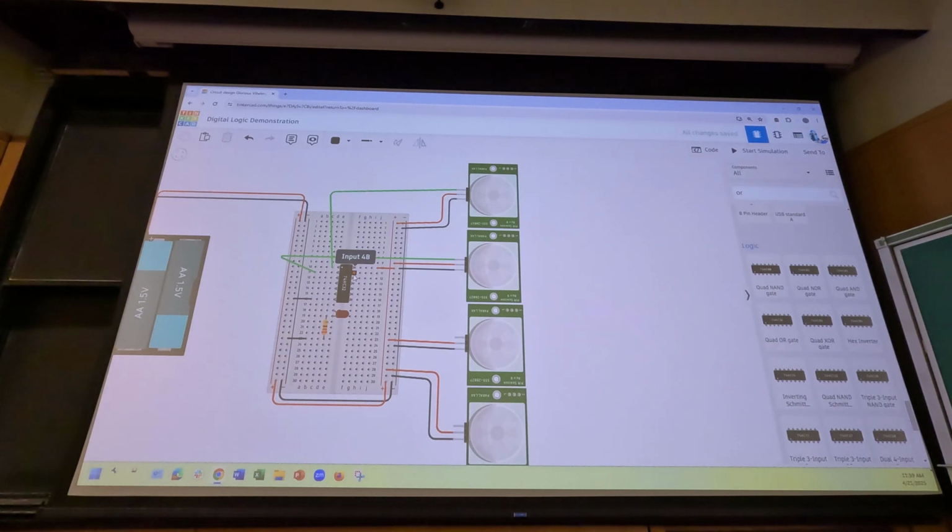There is a process to work backwards if you have some desired Boolean algebra function or result. If you have a giant truth table that has the outputs you want for all possible combinations of inputs, there is a process you can go through to figure out the minimum number of gates you need to accomplish that, which can be important for circuit design where you want to keep things as cheap as possible or have as small of a circuit footprint as possible.